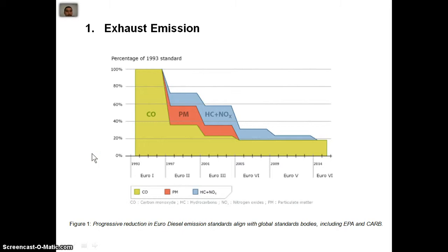For the engine management system, one of the main purposes is to keep the air fuel ratio very close to the stoichiometric point. That means 14.7 ratio for air and 1 ratio for fuel, which is the calculated air to fuel ratio. So by the way, theoretically at this ratio, all of the fuel will be burned using all of the oxygen in the air.